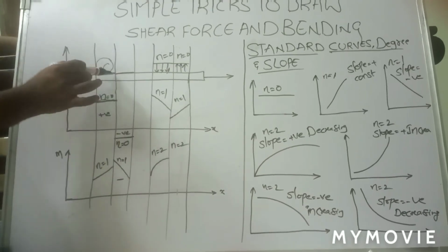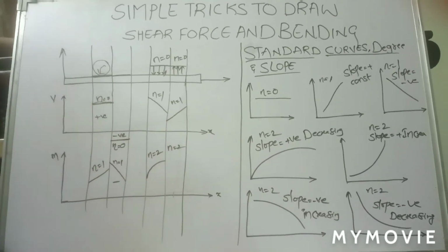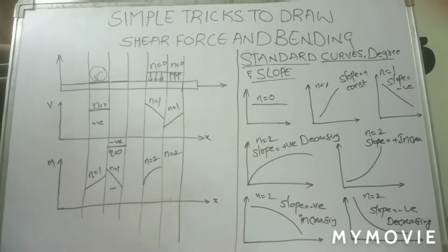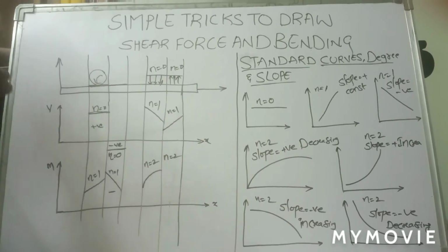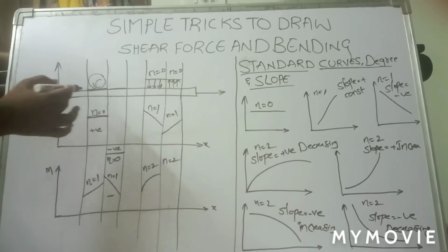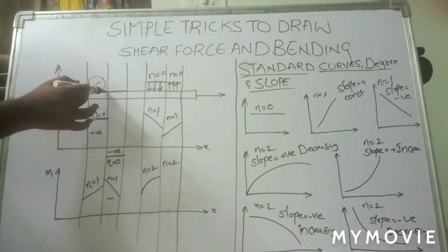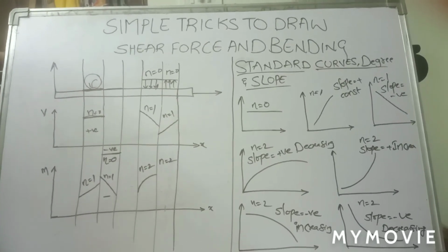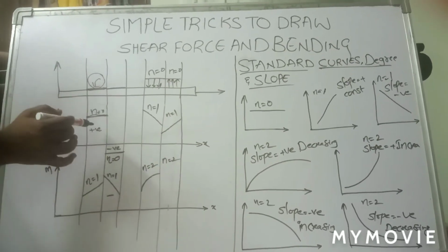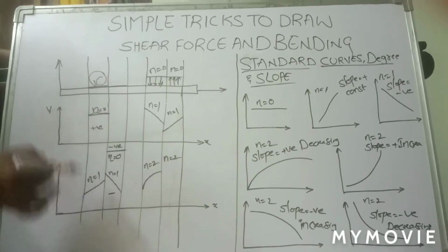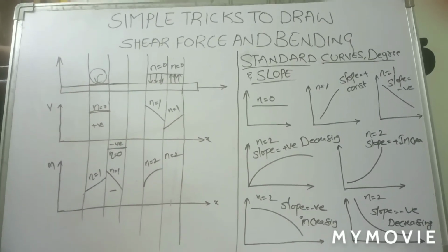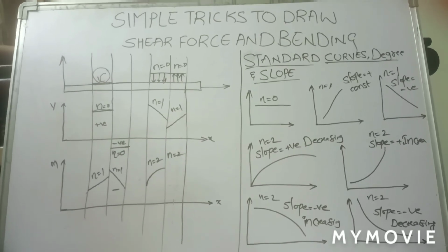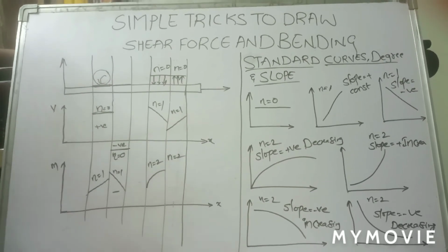In a beam we have a constant load or no loading condition. Constant loading means from point A to point B you have the same effect. With no loading condition, you have a straight line in the shear force diagram, so automatically in the bending moment diagram you have a slope, a straight line with a positive slope, continuously increasing.